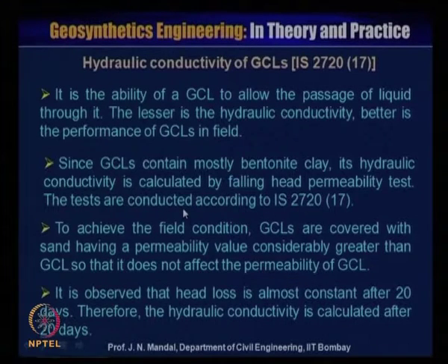Now hydraulic conductivity of GCL as per IS 2720 part 17 is the ability of a geosynthetic clay liner to allow the passage of liquid through it. The lesser the hydraulic conductivity, the better the performance of the GCL in the field. Since GCL contains mostly bentonite clay, its hydraulic conductivity is calculated by the falling head permeability test.